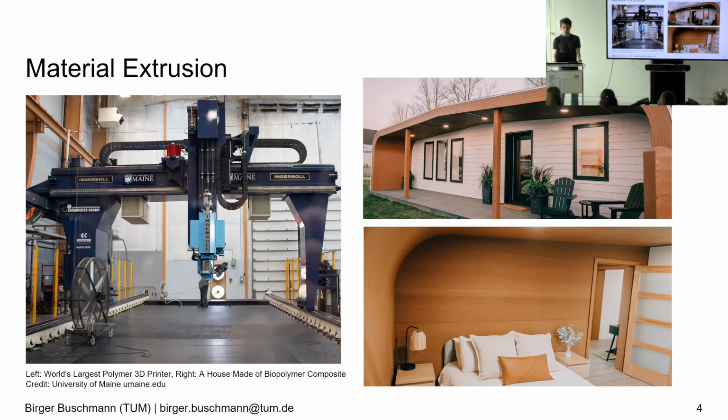In this process, molten plastic is extruded out of the nozzle. To this plastic, one can add around, let's say, 20 to 30 mass% of wood particles. Any amount higher than that is usually clogging the nozzles and is leading to reduced mechanical properties.